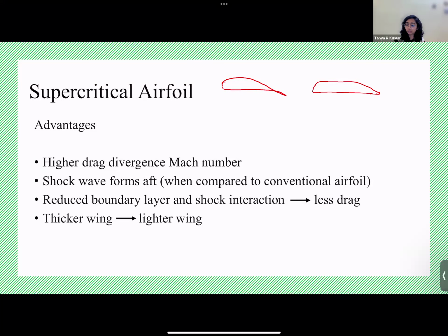In the positively cambered airfoil, maybe at some 0.7 you have a shock wave formed here. Let's say M critical was 0.7, and any flow above 0.7 will be supersonic over the surface of the airfoil and would give you undesirable flow separation and all of those undesirable traits. It doesn't give you as much lift as it should.